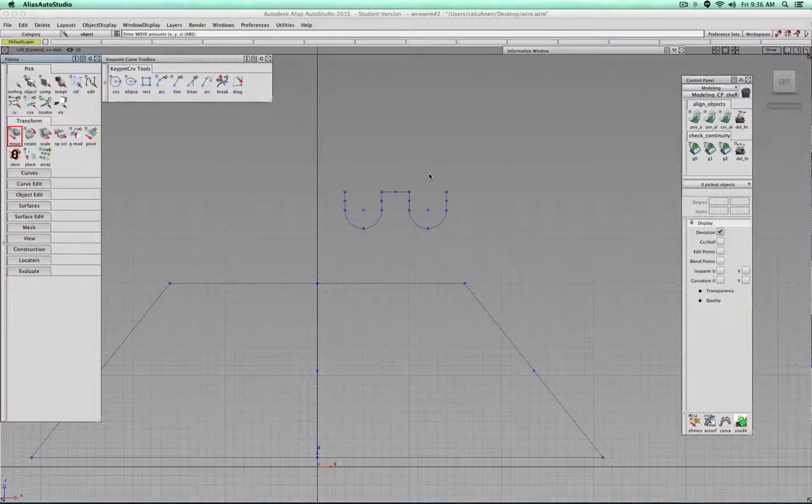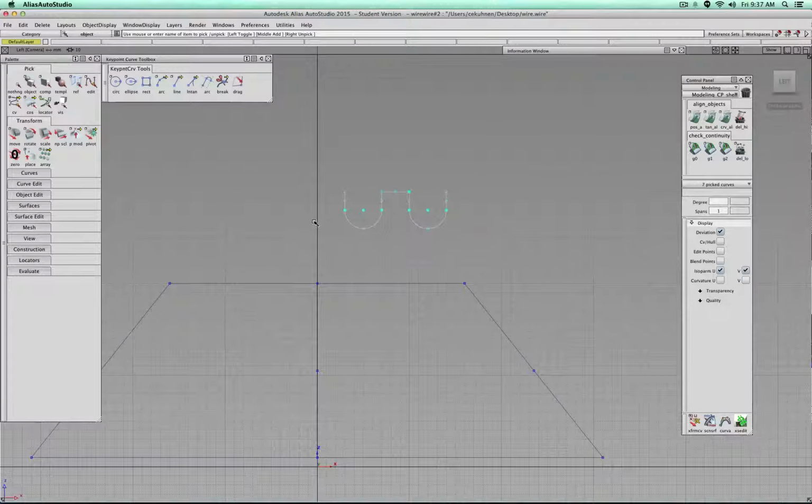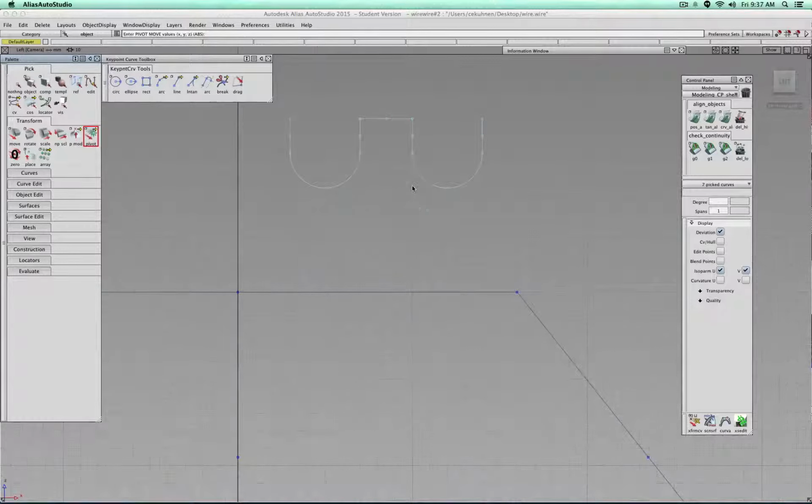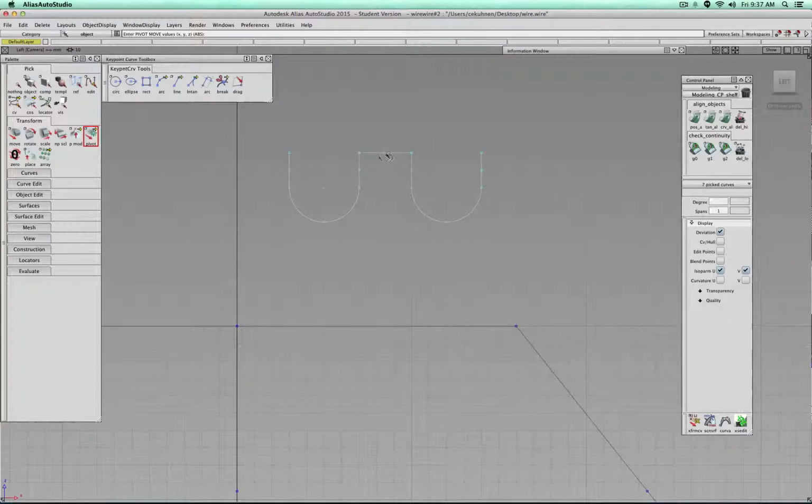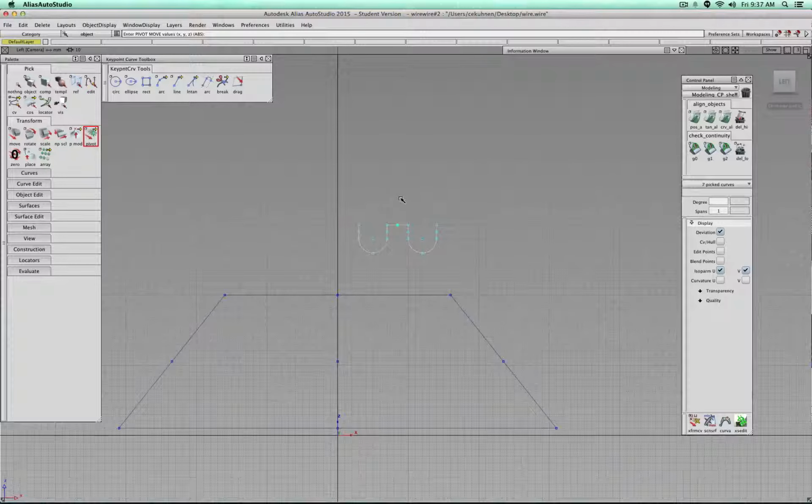That was just a helper. And then I'm actually selecting all those and create another group, because now actually I need to position this 3mm line on here. So middle mouse button, Control and Alt and left, and I'm clicking on this line because I want to snap the pivot point right to that center.